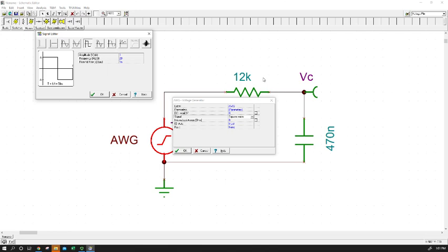If we look at that and say that is going to correspond to maybe 60 some odd percent of one half of the wave period, we could say, okay, let's double it and then double it again, and we should have some measure of what the total time is that corresponds to the whole period. So let's multiply it by 4 and we get 0.022. That would be a full period. So we know we want a frequency that will give us a full waveform that takes at least about 0.022 seconds. If I do an inverse of that, I get about 44. I'm going to cut that in half just to be sure, and that's going to give me my 20 hertz.